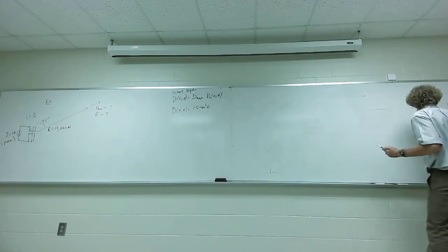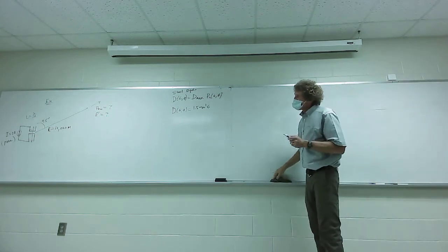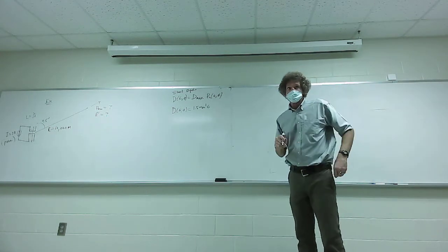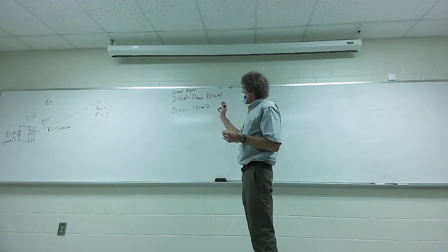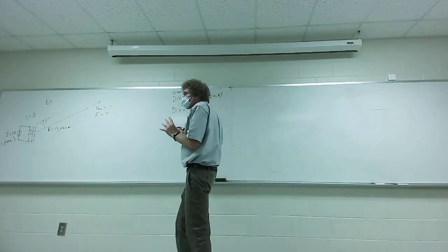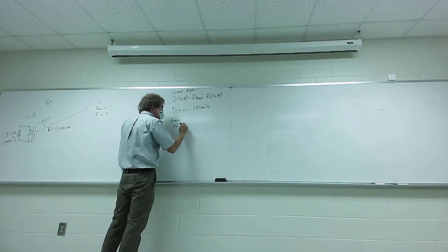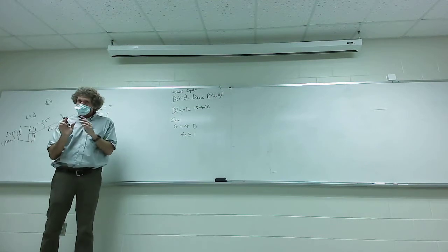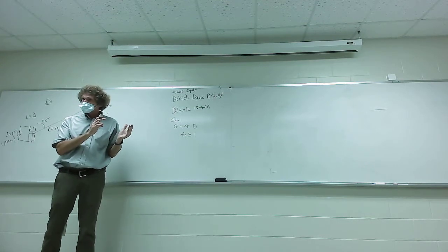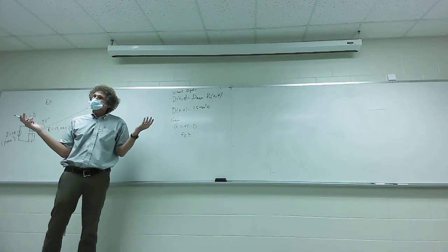And when I was in your position, when I started to see the overall purpose of a lot of this, it really started to make sense. But sometimes you're in there in the weeds and you don't see why you're doing it. All right, so I've got to say one more thing. There's something called gain. Don't worry about it. Gain is really an efficiency factor times directivity. And the efficiency is almost 100%, so it's almost 1 all the time. Gain is the more proper term used for what I'm going to show you. But a lot of people use directivity and gain interchangeably because the efficiency of the antenna is assumed to be about 100%.